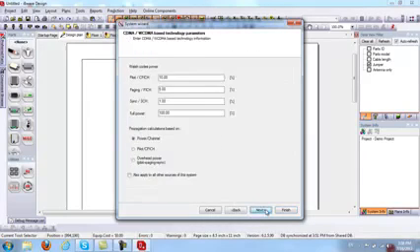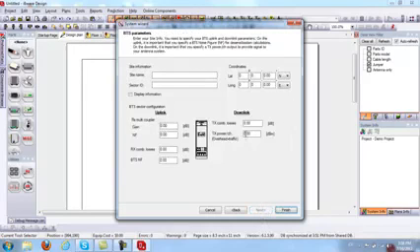And if I click on next, here I can specify whether I want my propagation calculations to be based on power per channel, pilot per chip, or overhead power. I will do pilot per chip. Here it comes up with some default values, and you can change them or keep them as you like. Once you go next, here you can put your base station output power. So I'm going to put 43, for example. You can put your noise figure. I'm going to select the value 5 dB.